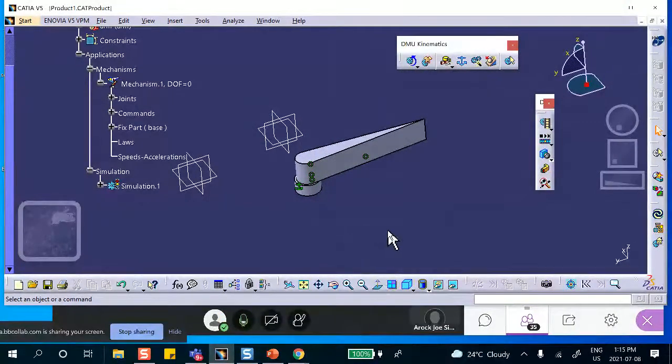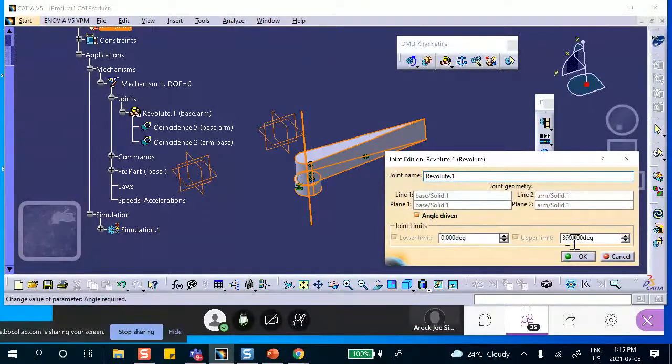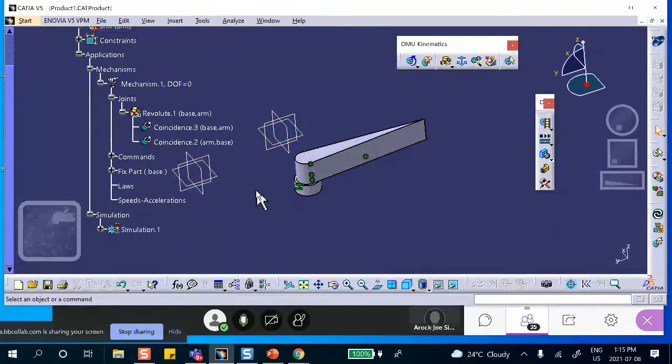Excuse me, Professor. Yes. I just had a question. I noticed that the videos end after 1 cycle. Is there any way we can make it do multiple cycles just so it's obvious what's happening? Well, first of all, multiple cycles is just going to be a cartoon. It's going to be a repeat of the first cycle. But my point is that the angle-driven joint, remember I made this thing angle-driven from 0 to 360. If you make it 720, it will go twice. It's another cartoon, repeating the first one. Okay, thank you. But that's just a cartoon.